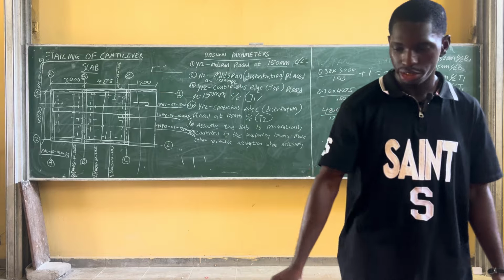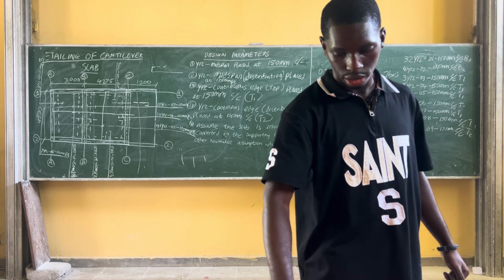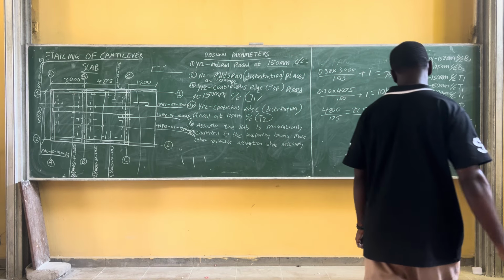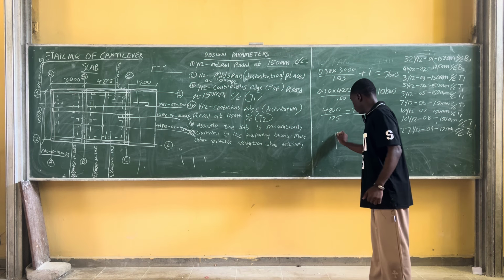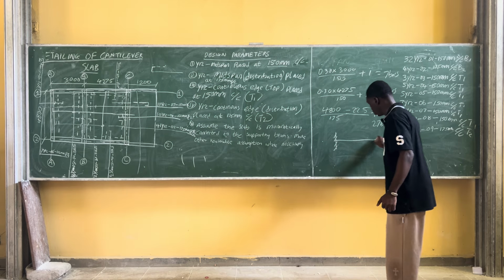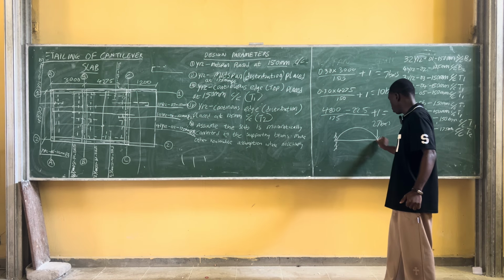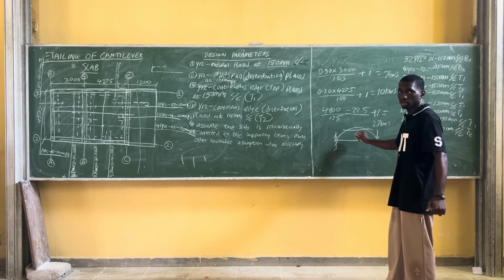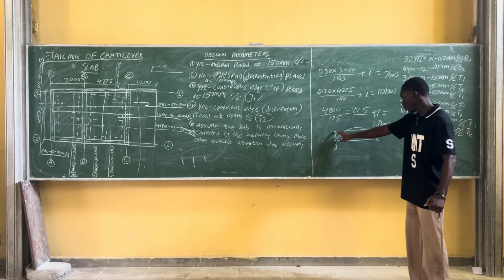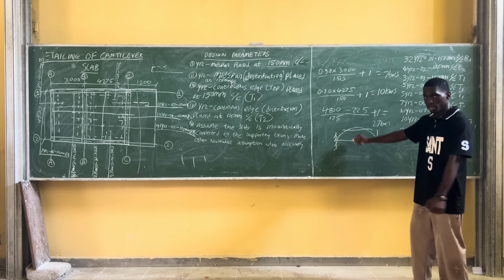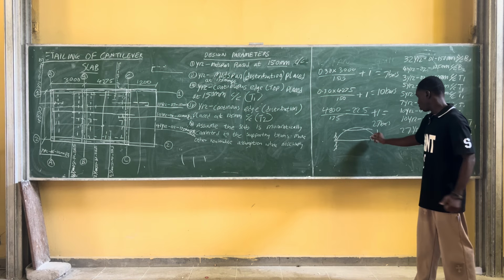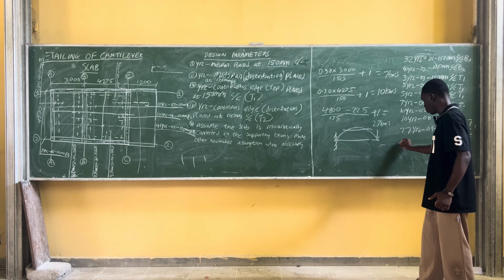Now at the ending, see how the reinforcement is. You know that this is a cantilever. Let me draw on the board. This is a cantilever. This is a fixed support. And see the force that is acting on it, making it deflect. And we are putting a reinforcement here. So our primary concern is this top reinforcement to prevent it from hogging. That's why I'm putting this reinforcement here at this top.